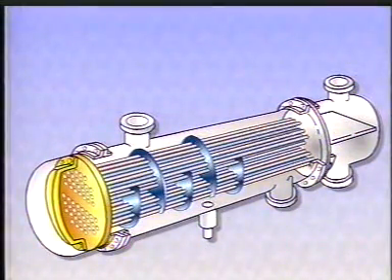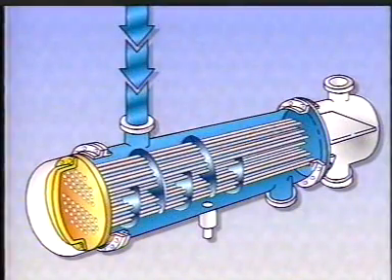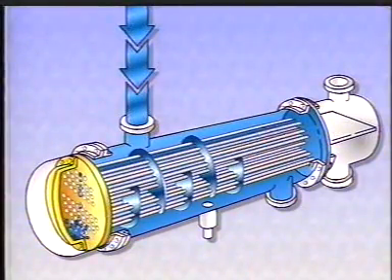If tests indicate a leak, the exchanger must be partially dismantled to determine its source. To find a leaking tube, the shell is filled with water under pressure. This water will enter the tube at the point of the leak and then run out the tube end. By watching the tube sheet, you can often tell exactly which tube is leaking. These procedures will help ensure proper operations and warn of problems before the situation gets out of hand.